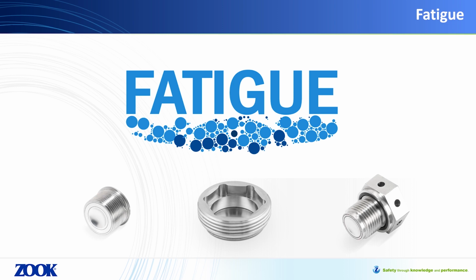Another cause of fatigue can be operating ratio. It's important to understand marked burst pressure versus specified and manufacturing design range to ultimately know what pressure level of disc you will receive, and to ensure that the rupture disc you have is properly spec'd for your installation. Discs installed in systems that will be exposed to vacuum or back pressure put added strain on the device. This push-pull effect can lead to a reduced service life. It's important to let your rupture disc sales engineer know full operating conditions so that your manufacturer can supply the best product solution. Various disc designs or options will perform better in this condition.